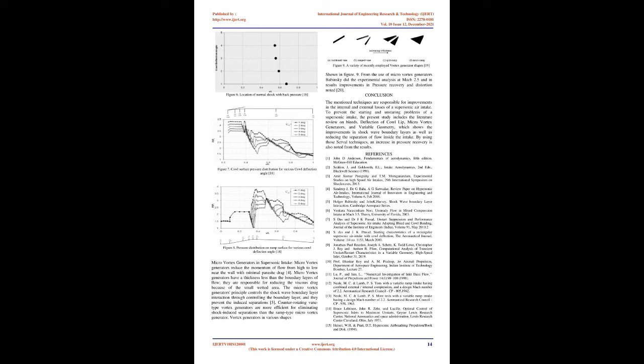Results. Controlling the mass flow in the intake is the primary solution to the intake unstart. Through variable geometry, mass flow is controlled, and Neal and Lamb did the experimental studies. There have been improvements in the results. Another solution to controlling the unstart of the intake is to provide the intake's bypass doors, which are used to release pressure during necessary conditions. As shown in Figure 3, the bypass doors work for controlling the mass flow.